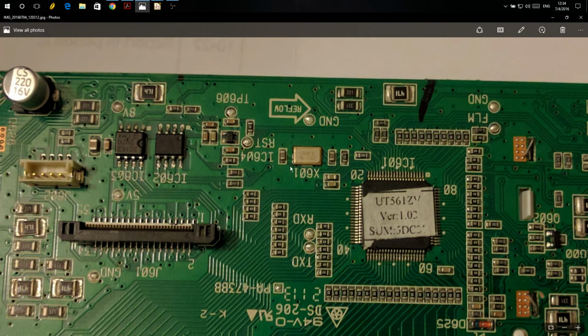So anyway, if that's okay, the next thing you're going to check is, do you have clock? And if you have clock, the third thing you typically would check is, are any of the buses dragged down? Like these two pins and this guy right here, the EEPROM, are going to be clock and data, and these are typically pulled high. So these are going to be fairly close to your 5-volt rail. If these are dragged low, you're going to have boot problems, particularly when it's trying to read an EEPROM and it can't. That's true for a lot of things, not just this radio, but even the aforementioned receivers.